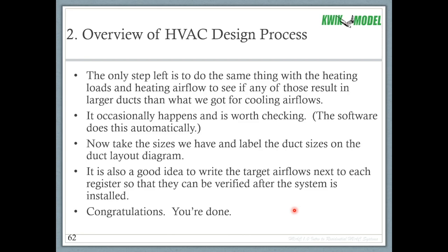One of the most valuable pieces of experience that I got in my career was we did a lot of designs for production homes, and we wrote the target airflow next to each register, and then we had people go out to the houses after they were completed and measure those airflows, and on the plans they would write the measured airflow right next to the number that was printed on the plans, and then they would send that back to us, and we were able to go through and look for problem areas.